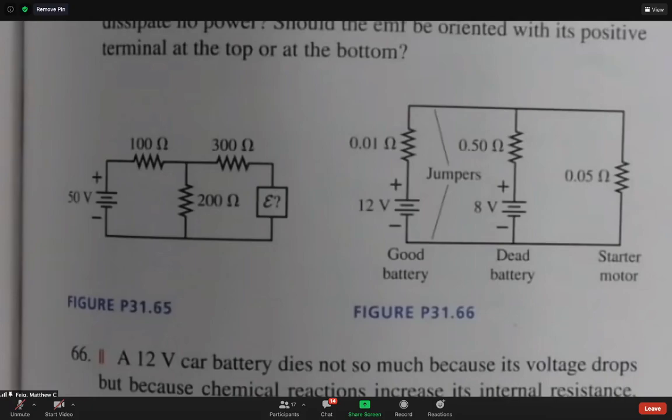It was 900, 720, and 360. And if you have 0 current in the top branch, then the 900 value becomes fairly unimportant because it gets multiplied by 0 current to give you 0 volts and 0 power. But the important ones were the 360 in series with the 5-volt battery, and the 720. Basically because 720 is double 360, the one voltage would have to be double the other one. So double 5 and get 10. So we're seeing something like that here.